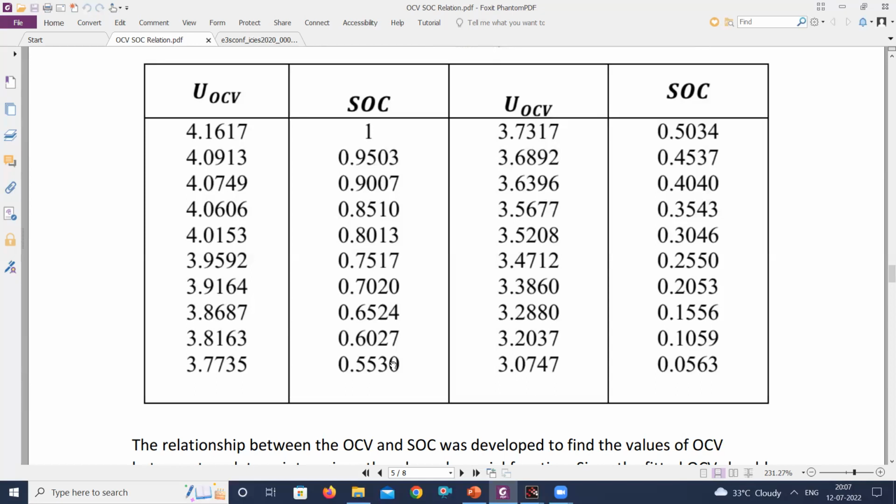The nominal voltage that we consider, because of transportation. The transportation happens at 40% SOC, and once you are storing the cells, they should be kept at 50% of it. So that's the same value that comes. That's why, also, one thing you need to remember always: whenever you purchase a fresh cell, the voltage should always be at 3.7 volts, like 3.7, 3.69, 3.71, that could be the maximum.